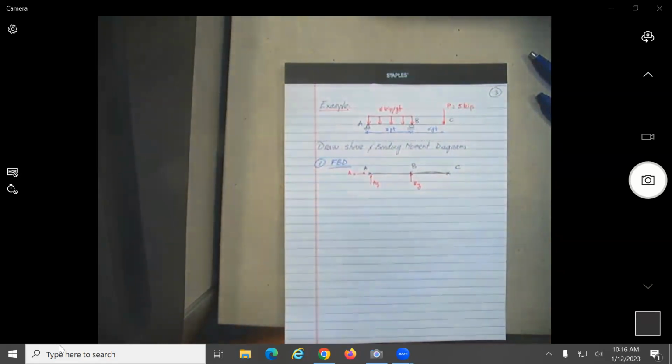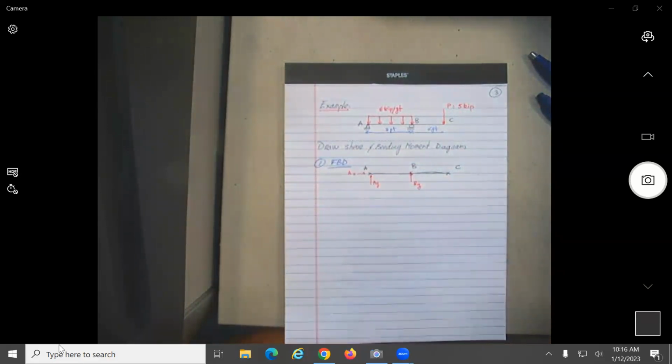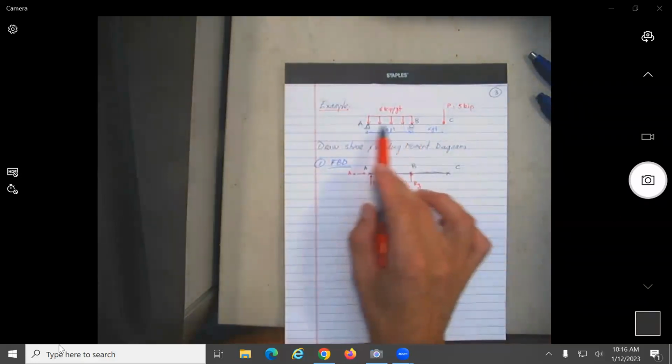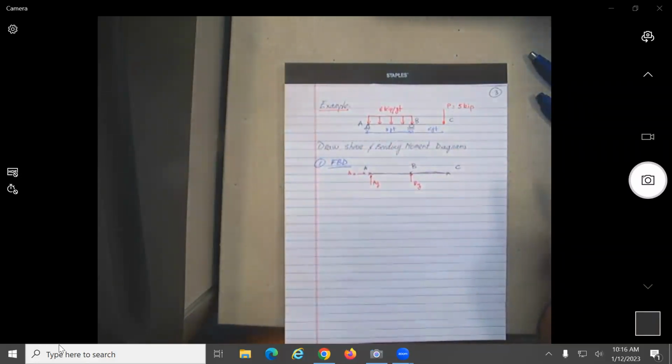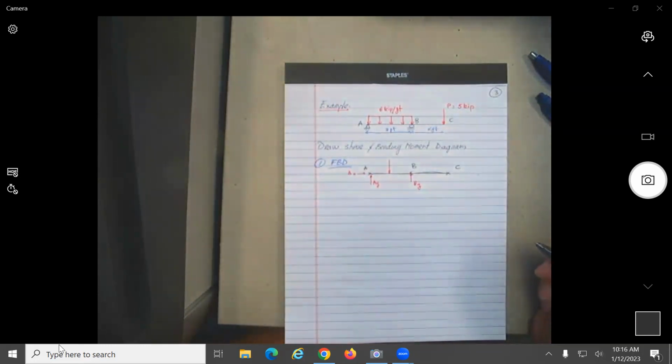So here, if you want, starting about your head, how many unknowns do we have? 3. Statically determinate, we can solve it, no? Maybe we'll do some statically indeterminate, but so far for the review, no. Okay. Now, can I replace this distributed load by just one force? Okay, how do we do that? Okay, so we move it to the center. What would be the magnitude? 6 times 8.